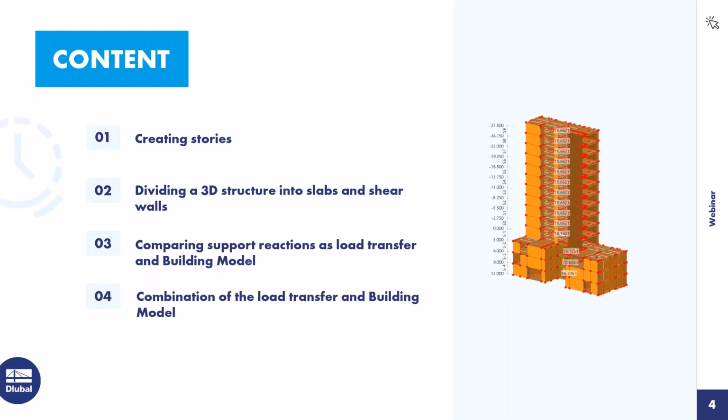So the nine stories on the top are smaller than the 3 stories in the bottom, and therefore it is recommended, or in my opinion it is the best way, to analyze this bigger cantilever or balcony outside with this bigger area with the 2D analysis. And in this way I can combine 3D and 2D calculations.